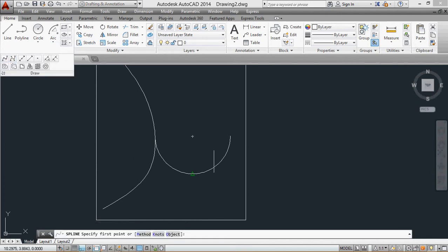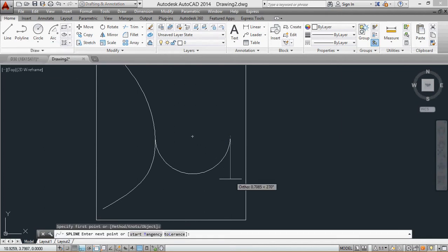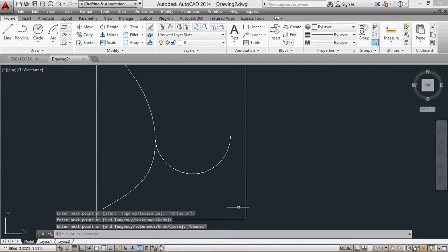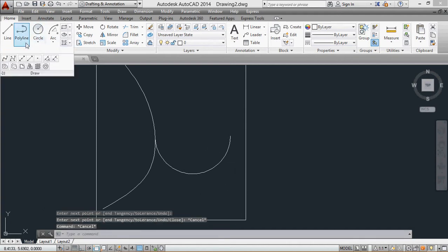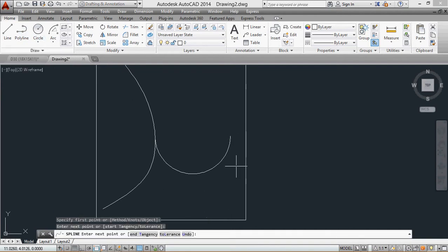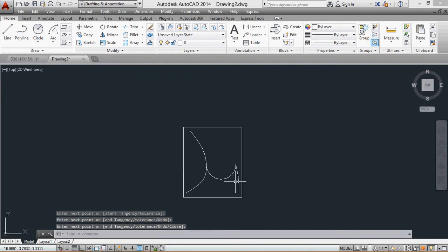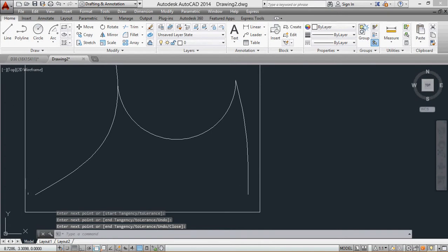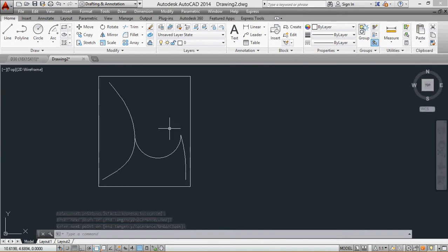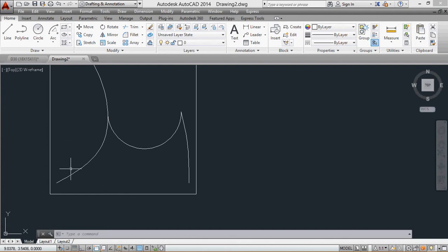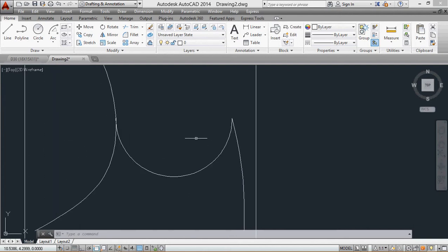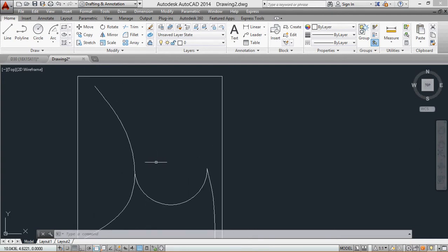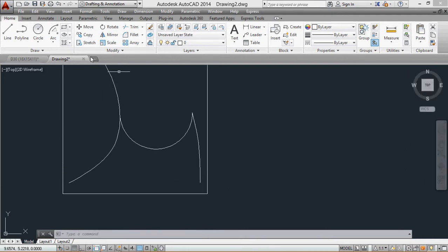Go to spline, because I want to make it unique. Turn off my ortho, I no longer need it, and I go to somewhere down. Now the part, oops, forgot to click enter. What you need to make sure you do is when you have that piece down here, is that these are aligned. Otherwise, when you have it on your table, the backs can be higher or the fronts can be lower. Even though at this shape, your phone should be at that same angle, as long as the bottom parts are the same angle. So what we can draw is a line.